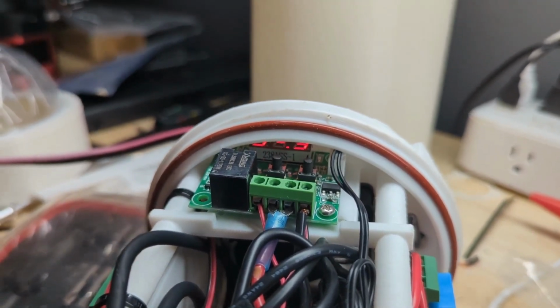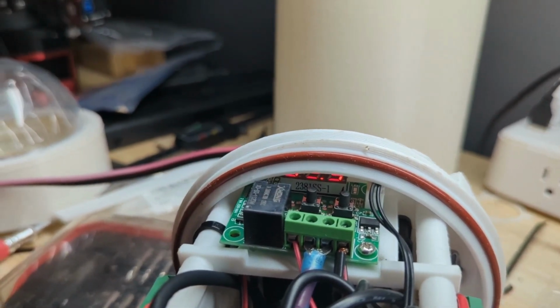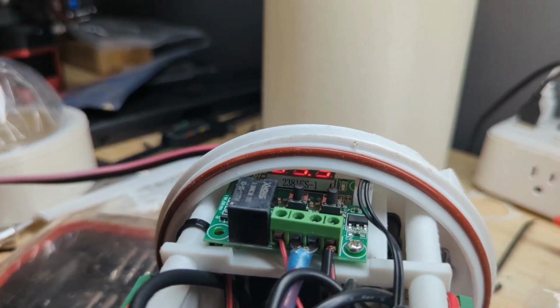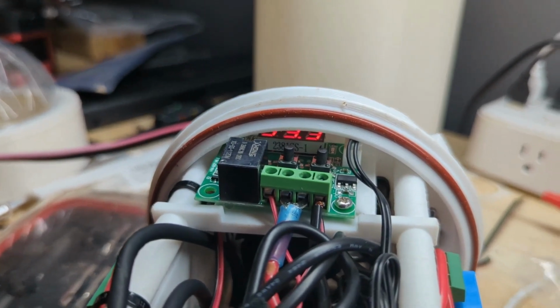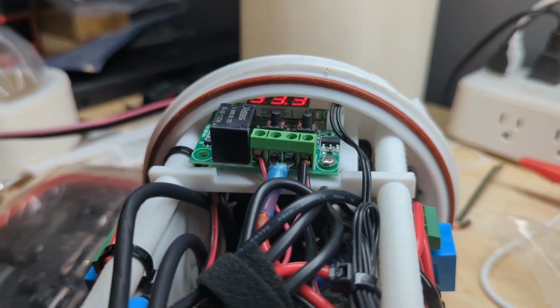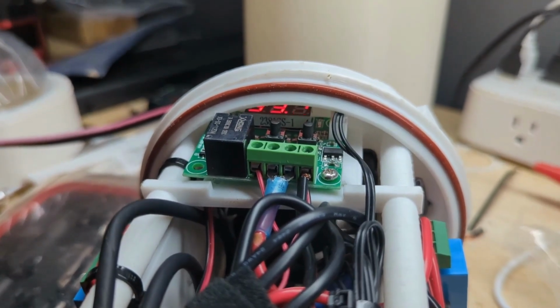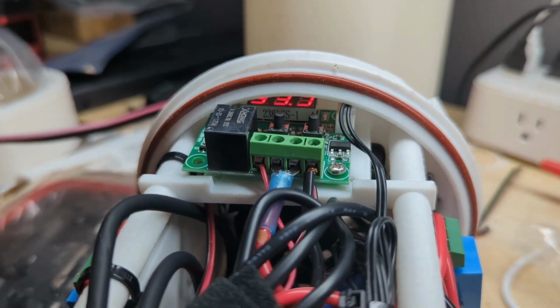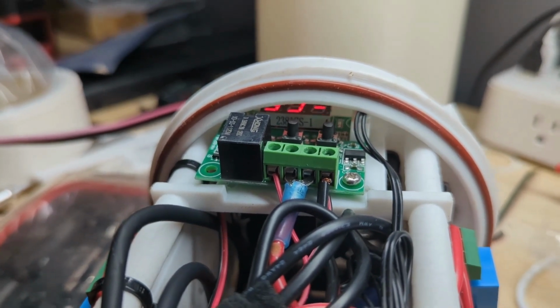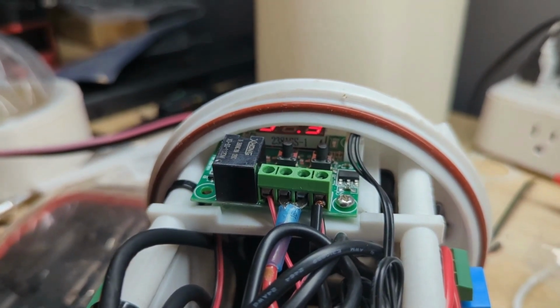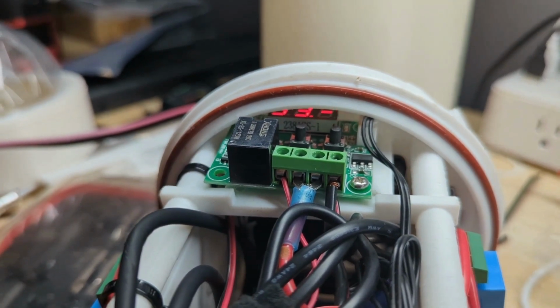If you set it at 95 degrees, as soon as you hit 95 degrees again, it would shut off, and it would be a constant on-off process, which is not what you really want. So it waits until it hits 2 degrees above your threshold before it turns on and cools the system. Once it gets back down to your threshold, then it turns off.